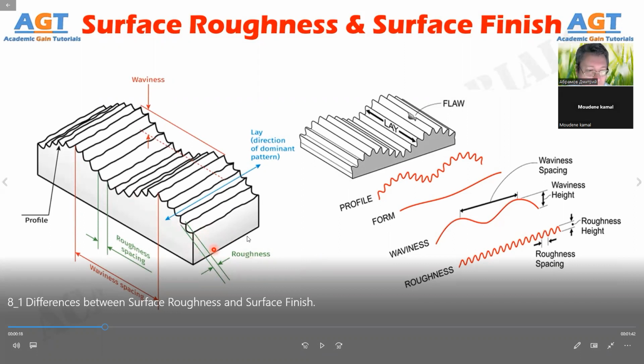In this figure, you can see the real form of the part. We can see the profile of the surface, form of the surface, waviness, and roughness. Roughness height, the value of roughness in micrometers.